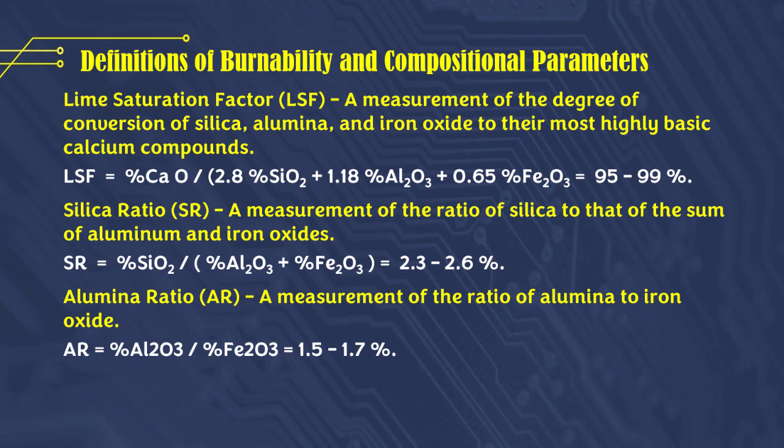Definitions of burnability and compositional parameters. Lime saturation factor, or LSF, a measurement of the degree of conversion of silica, alumina, and iron oxide to their most highly basic calcium compounds. LSF is %CaO divided by 2.8% SiO2 plus 1.18% Al2O3 plus 0.65% Fe2O3, normally equals 95 to 99%.